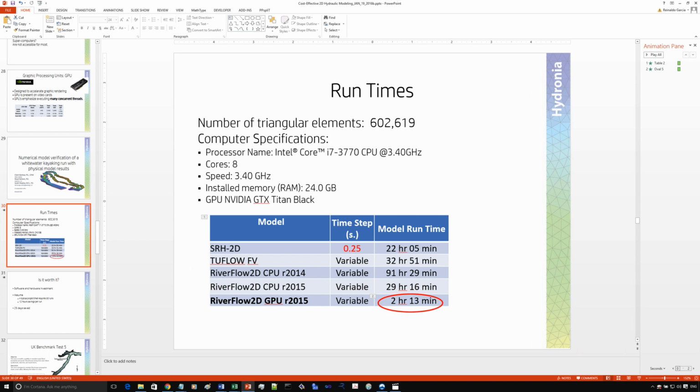Okay, another question here: is it possible to work with different meshes of the same computational domain? Yes, you can refine the mesh. You can set different resolution in different areas. There are many tools to do that, where you define a polygon and you want smaller elements in that area, and that's obviously possible. Yes, and it's very common. Obviously, I used just in the example a very simple uniform mesh, but in general, that's what you do.